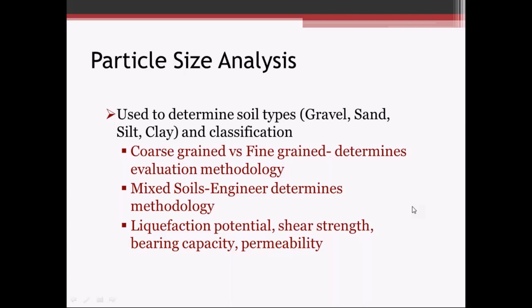Depending on if the soil is coarse grained or fine grained, that's going to dictate the methodology that the lab will use to determine shear strength and soil settlement parameters. If the soils are mixed, with a combination of fine grain and coarse grain, then the engineer needs to determine the methodology based on how they think the soil will behave, more as a fine grain or more as a coarse grain soil.